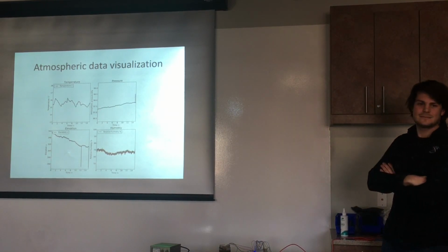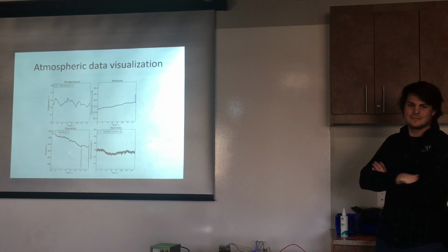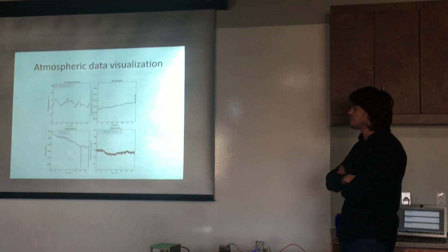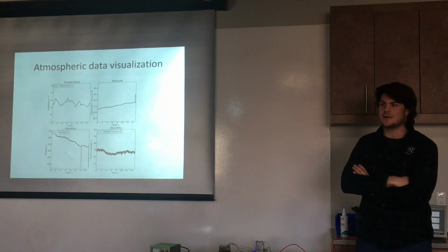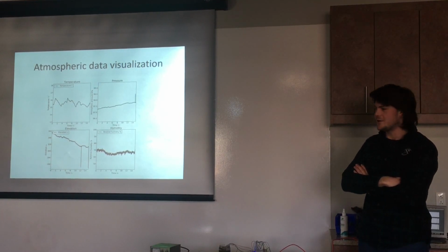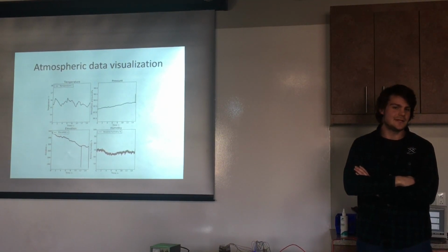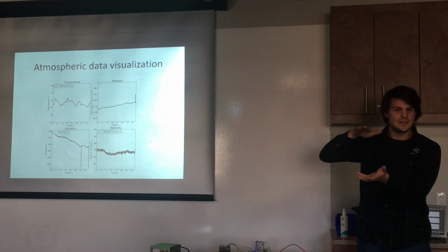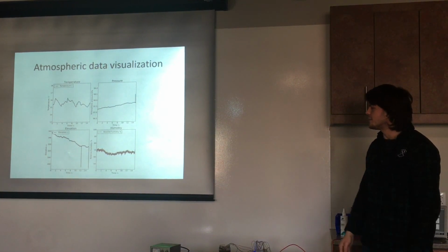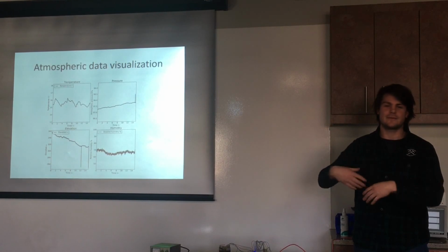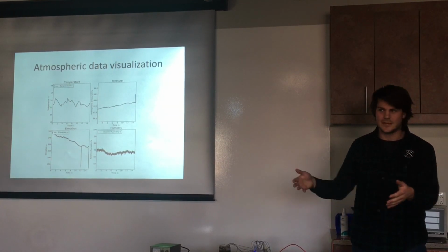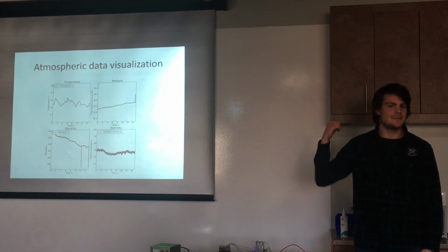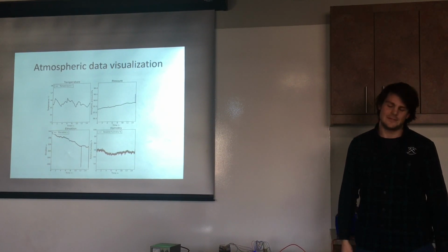So how did you calibrate your soil moisture, 0 to 100 percent? I defined 0% saturation as completely dry F110, and then 100% saturation as colloidal F110, so basically up to the critical porosity where it becomes basically a mud. I just assumed it was a linear scale, which it might not be, and then took the ratio of whatever value I got out to the maximum, and that's my percent. So 2-point calibration. 2-point calibration.